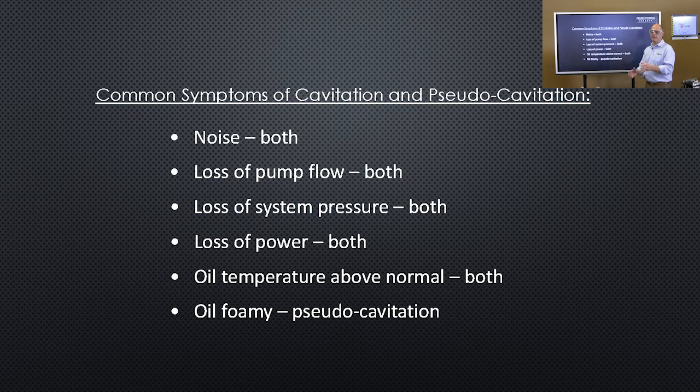Well, that's fine if we're looking at what's going on at the inlet side of the pump. But if you take a gaseous cavity through the pump, and on the other side of the pump it's going against a resistance of 1,000, 2,000, or 3,000 psi, there's no doubt that that gaseous cavity is going to implode. And the force of that implosion is not measured in pounds of force per square inch, it's measured in tons of force per square inch.